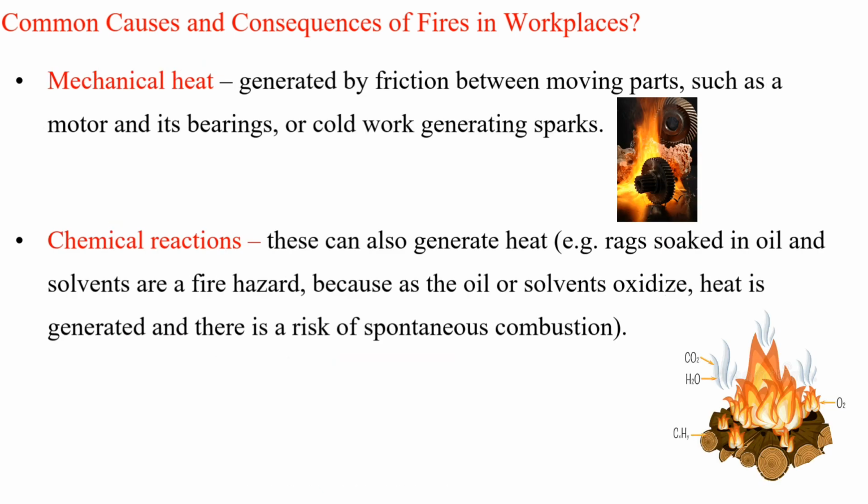Mechanical heat. Generated by friction between moving parts, such as a motor and its bearings, or cold work generating sparks. Chemical reactions. These can also generate heat. For example, rags soaked in oil and solvents are a fire hazard, because as the oil or solvents oxidize, heat is generated and there is a risk of spontaneous combustion.